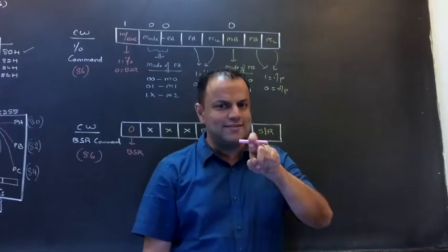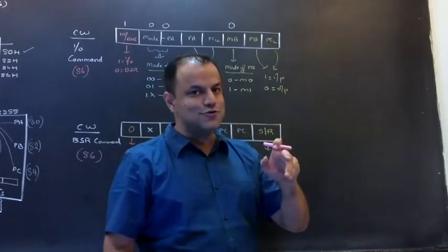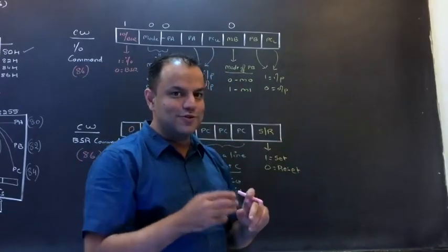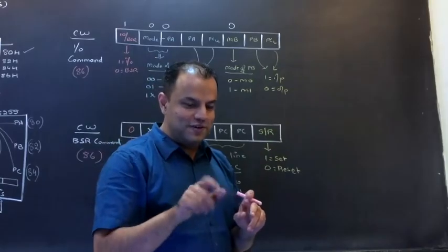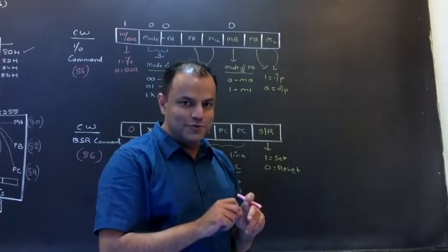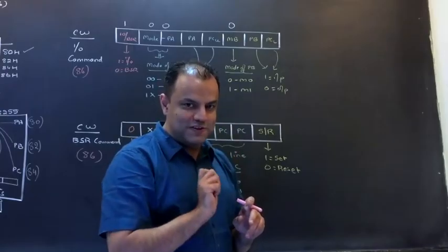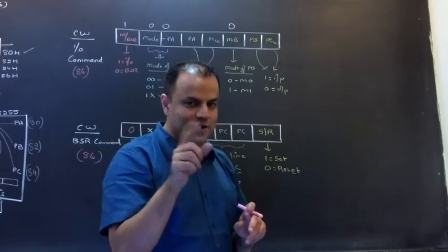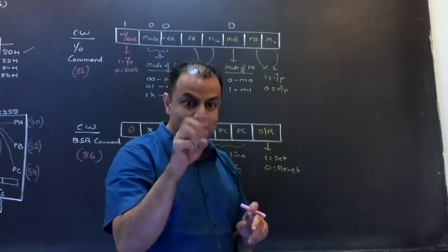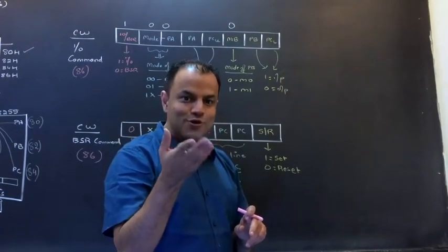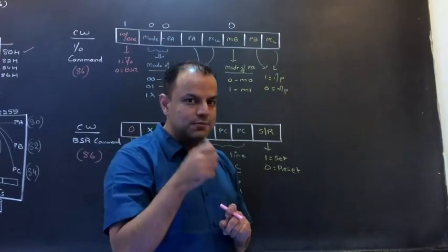Do you all understand this? Now, is that a good thing? Of course. So what happens? You send something, it stays on the port. On your calculator, you do 2 plus 3, you press equals, the answer is 5. The processor calculated the answer. Through a port, it has sent it to the display. Now, should the processor keep sending 5, 5, 5, 5, 5? No, it will send 5 once. Should the 5 come and go? No, it should stay. Who is holding it? The port is holding it. Tell me, did you understand?